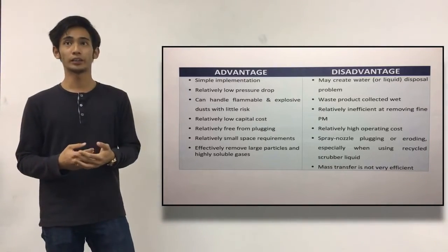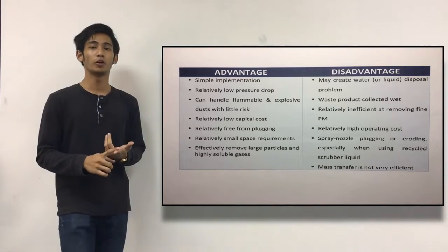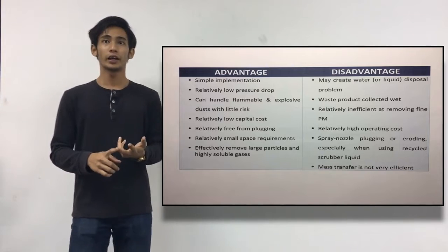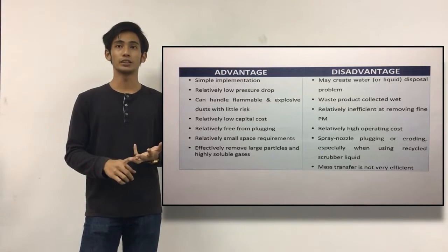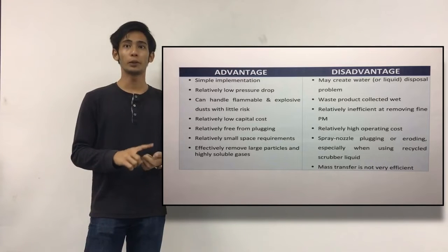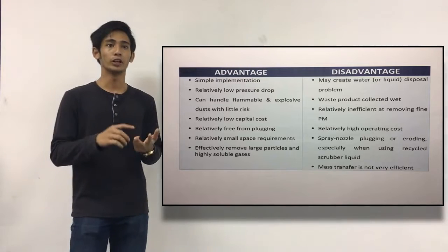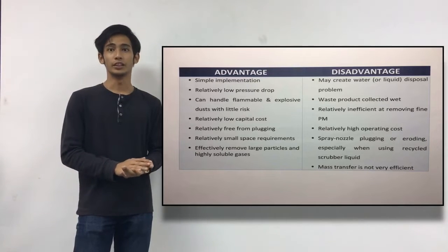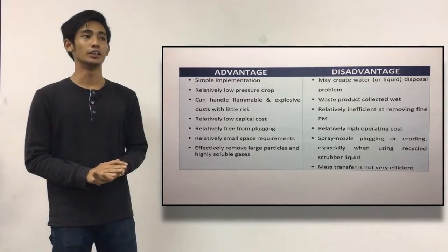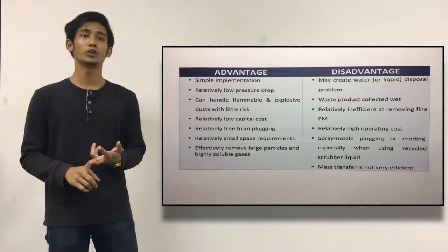Okay, the spray chamber has a simple implementation. Next, it has a relatively low pressure for the operation. It can handle flammable and explosive dust with little risk. It relatively has a low capital cost, is free from plugging, and has a small space requirement for the equipment. Lastly, the spray chamber can effectively remove large particles and highly soluble gases.